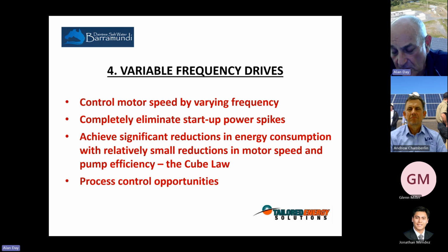So, putting it in the context of a barra farm, for instance, if you've got this kind of saltwater intake, you could put a level sensor at the intake, which is basically measuring the tide height, and you could use that to feed back to the variable speed drive, which will change the motor speed to maintain the operating conditions you want. This is about the famous pump curve. But you can maintain the speed, just make it constant through that process.